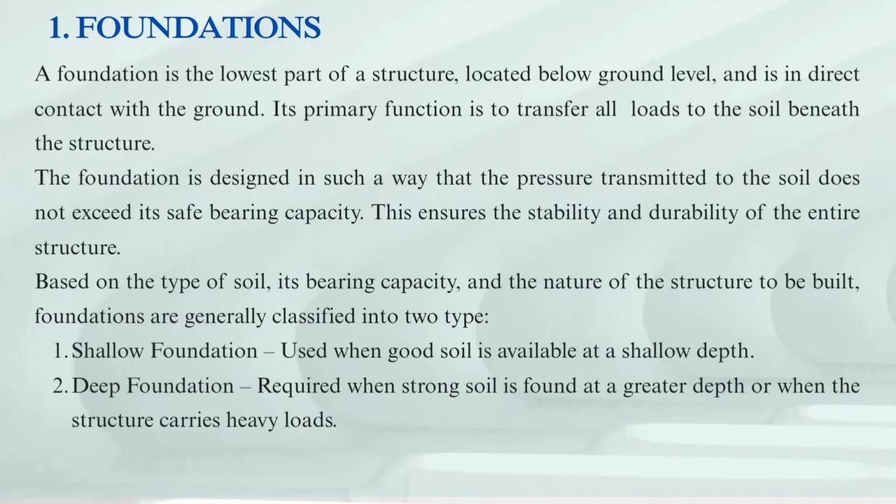Based on the type of soil, its bearing capacity and the nature of the structure to be built, foundations are generally classified into two types: shallow foundation and deep foundation. Shallow foundation is used when good soil is available at shallow depth, and deep foundation is used when strong soil is available at a greater depth or when the structure is carrying heavy loads.